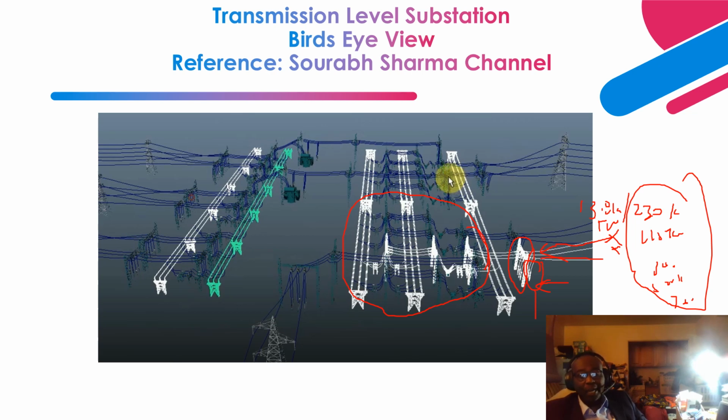So that is why we have a lightning surge arrestor right at the entrance of the substation. Its goal is to basically protect the equipment that is located in this substation. When it is in normal operating condition, right, it has a high impedance. It is connected in a shunt configuration, right, connected from line to ground. And when it is in normal operations, only leakage current flows, very small leakage current in the form of milliamps, right.